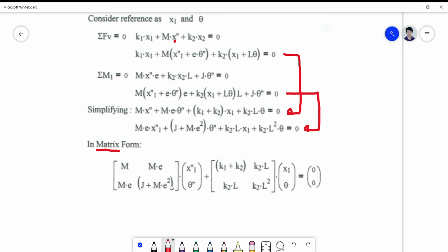Okay, and just take note that your matrix here on the mass, you call this now your mass matrix, and your stiffness matrix are not, okay, at all symmetric, and this gives us some difficulty, especially when the number of degrees of freedom is very high.